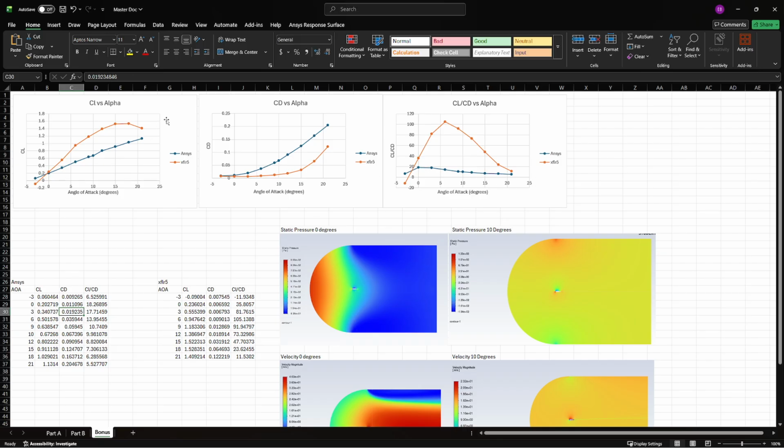It's almost as if our CL is growing at a similar pace as our CD, where it really shouldn't be the case. It really should be that as CL jumps, CD is jumping with it, but at a much higher rate. And this is because as you generate more lift, you're getting a negative effect of additional drag, that pressure drag that's coming from that increased surface area.